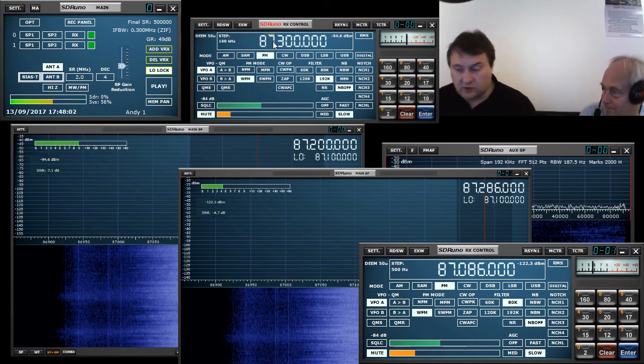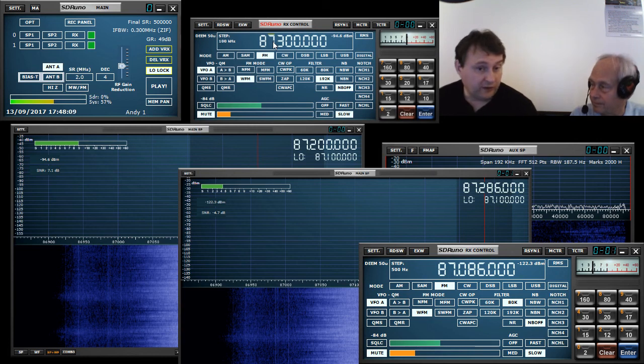The thing to note, particularly with AM signals, is whether you use 0IF or low IF, right? Because we've got the ability in the RSP to use either. If you're using 0IF, there'll be a hole in the spectrum, so you should make sure that the LO and the VFO are slightly offset when you're in 0IF mode. If you switch to low IF mode, that doesn't have the same issue. The DC spike. That's the DC spike.